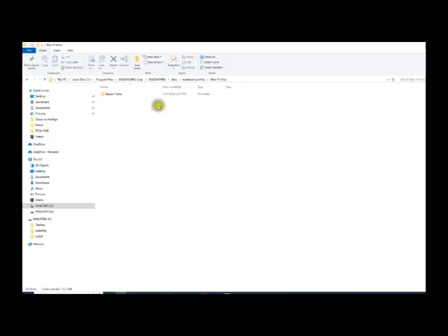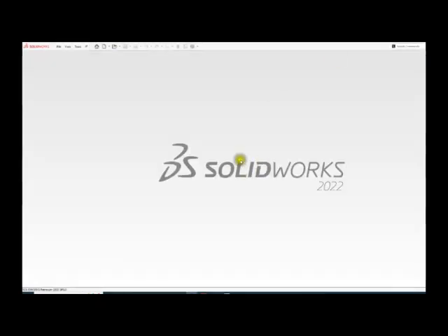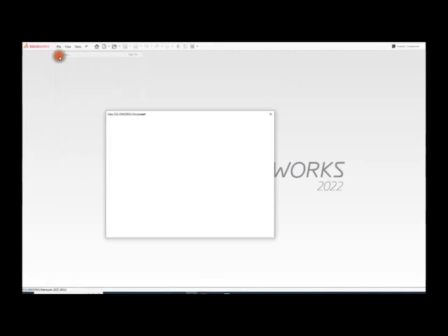So basically we need Weldment profile, new profiles. Inside new profile we're gonna get the square tube, and inside the square tube is the type, the pipe that we just created, in this case the tube. All right, so we are out of here again, and we're gonna go back to SolidWorks, create a new part,